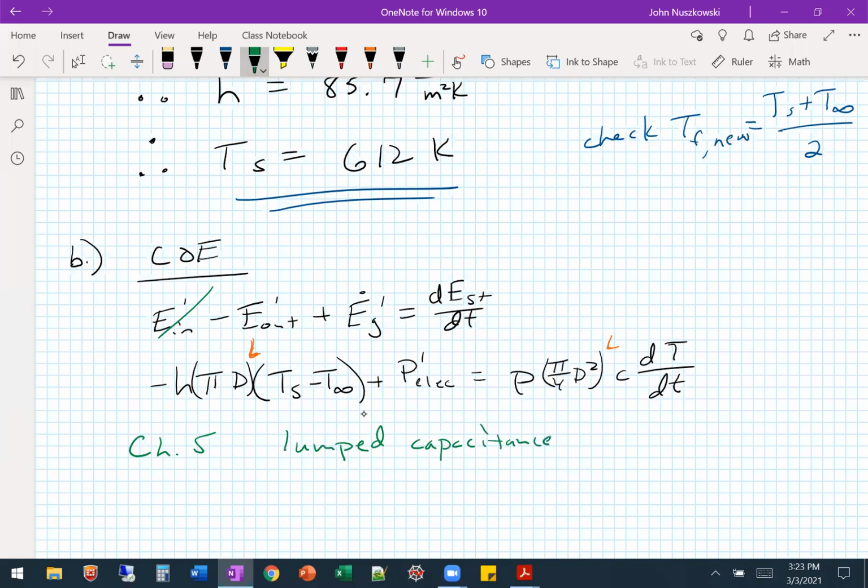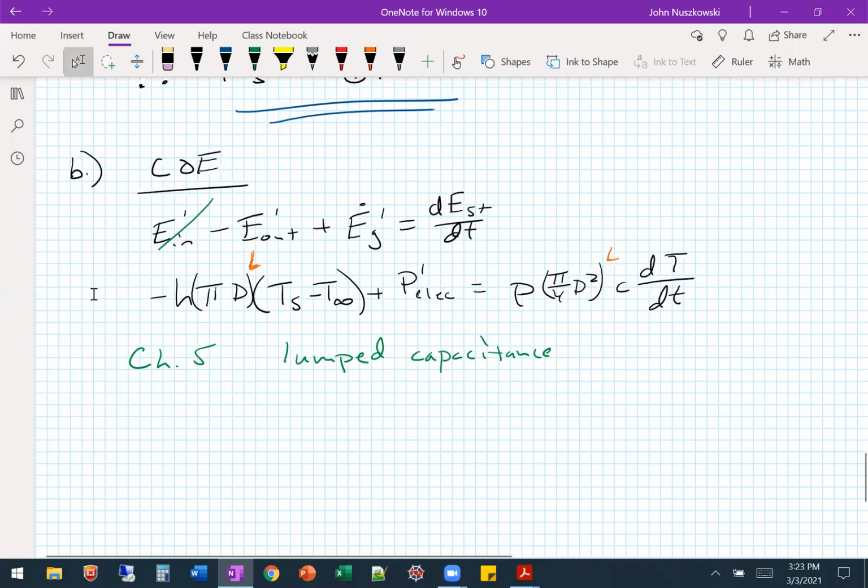All right. So we have transient. Transient, you first want to see if you can do lumped capacitance because it's the easiest transient analysis to do. And if you can't, then you start going into the more complex ones to get a correct answer. So lumped capacitance, which means everyone's favorite, we need to do our Biot number, right?